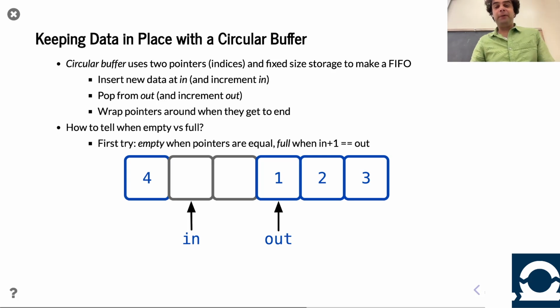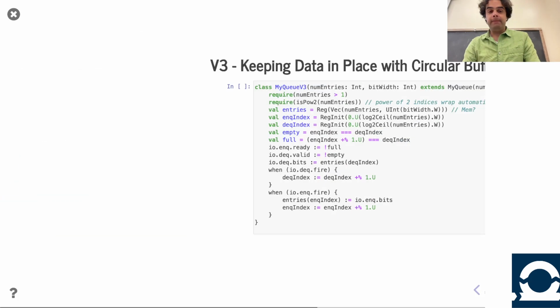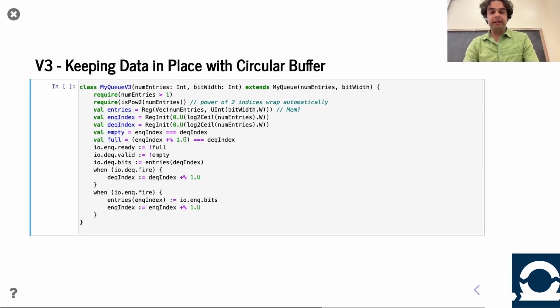But hey, we're getting a foothold. This new idea, we're building the circular buffer. It's the kind of thing, like I said, the circular buffer idea pans out. You implement this new approach. Hopefully, you see a reduction in critical path. Hopefully, you see a reduction in power consumption. If that's encouraging, then you have motivation to go forward and figure out this issue about using up that last entry, right? And maybe that last entry doesn't matter. Maybe you have 120 entries. Losing one entry you don't sweat, that's fine. But if you have only a handful of entries, maybe you care. So like I said, to what extent you can defer the heavy lifting until you know you need to do it, right? Cool. So how does this come together?